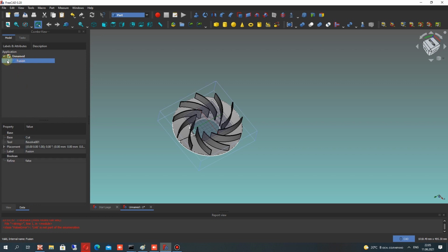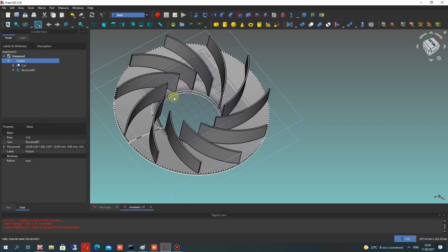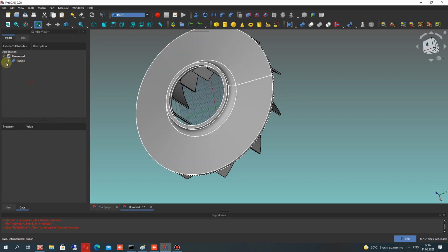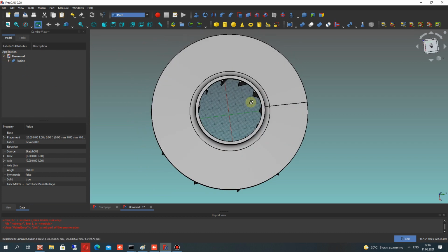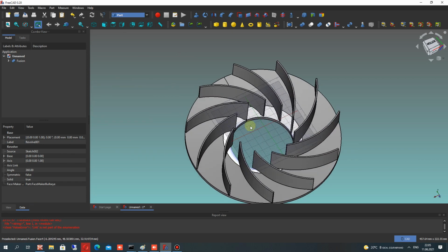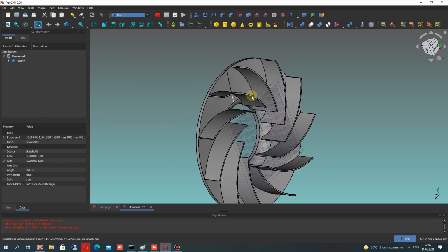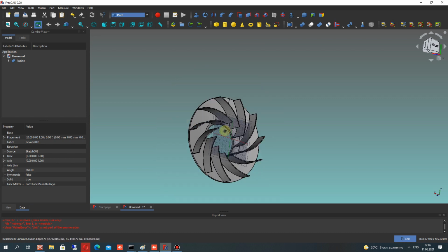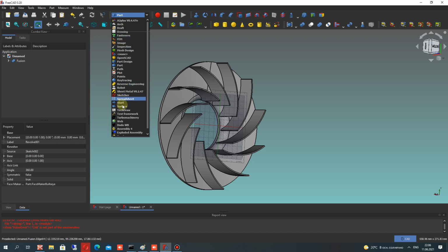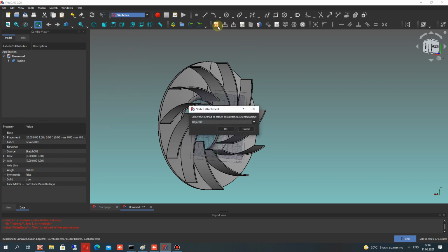A copy was created. Let's delete it, and let's activate the refine true. It will delete some edges for models. It makes a higher quality 3D model. Okay, as you can see, we have the Shroud and blades here, 3D model, and the next step will be creation of the hub shape.